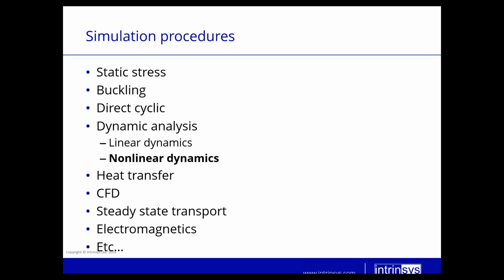So to begin with, simulation procedures. What everybody who has ever done a simulation is familiar with is the static stress. This is where you constrain your model and load it, and then you see the static deformed shape. This is the classic and also the simplest FE simulation you can have. However, there are problems